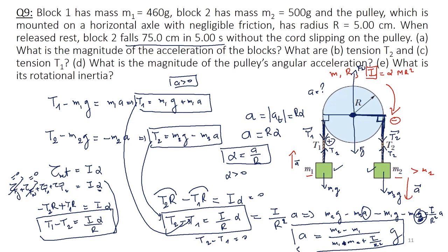But now the pulley is not massless anymore. The pulley is rotating, so it has a moment of inertia. So the pulley is favoring the rotation in one way. And always, always, always, the pulley is rotating in the direction of the dominant torque. So the tension T2 is bigger than the tension T1, because otherwise the pulley will not rotate in that direction.